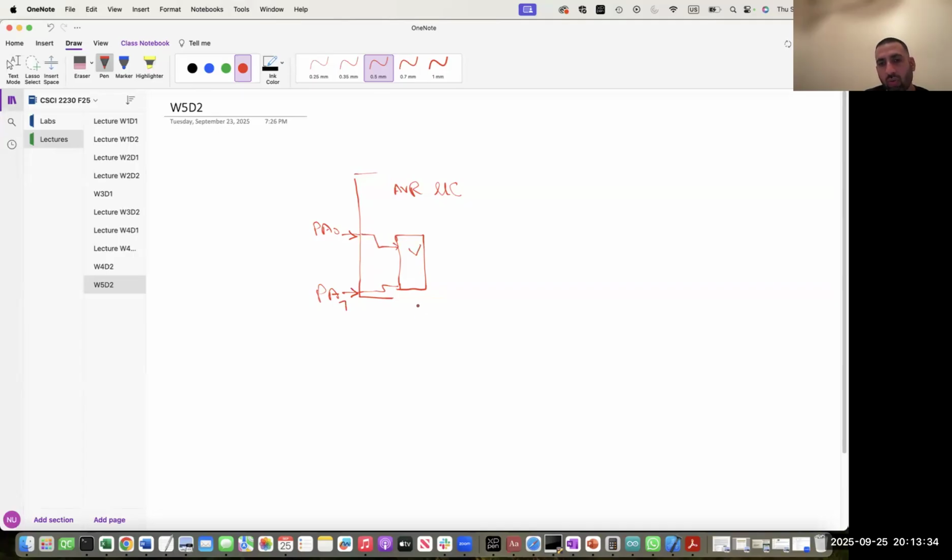If we don't wait for one clock cycle, and after configuring these pins in input mode we immediately want to read the data, then the data available will be older than one clock, the previous data.